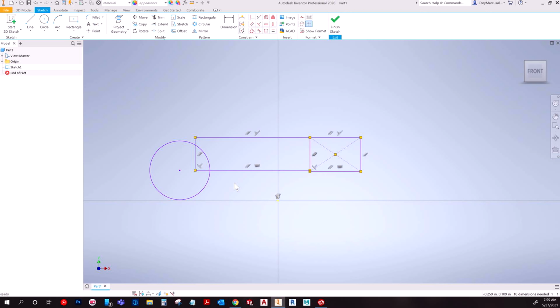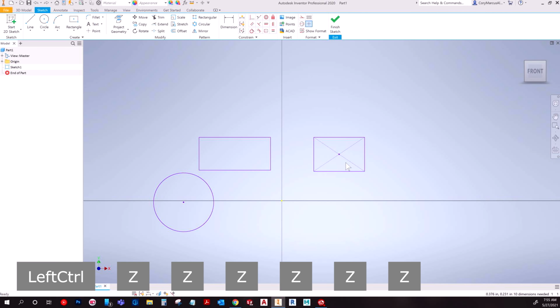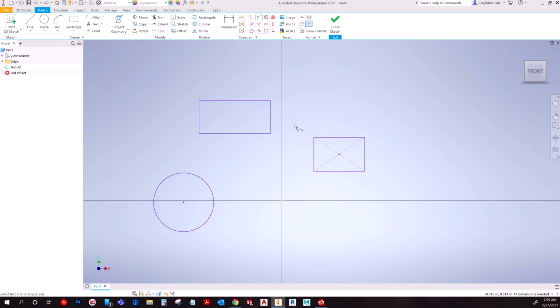And as you get better with Inventor, I'm hoping you will be too. But basically, that's the general practice with collinear, you're trying to align things. And it's really useful. It depends on what you're doing, but obviously the ability to just horizontally align or vertically align, or just to say way up here and way down there, they're connected in alignment. It's great.